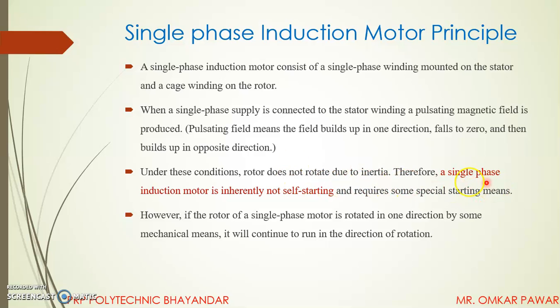Therefore, a single phase induction motor is inherently not self-starting. It will not automatically start to rotate like a three-phase induction motor and requires some special means. However, if the rotor of a single phase motor is rotated in one direction by some mechanical means, it will continue to run in the direction of rotation.